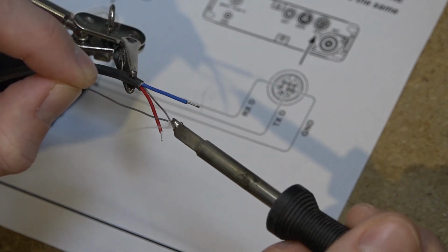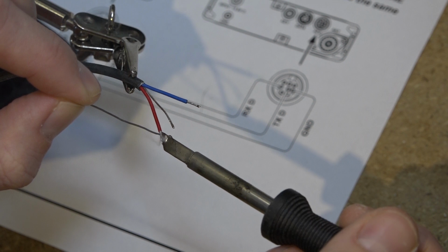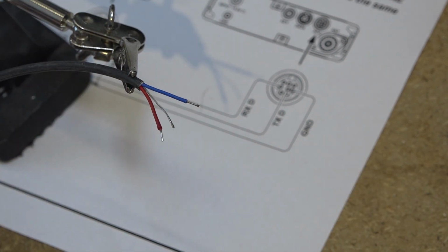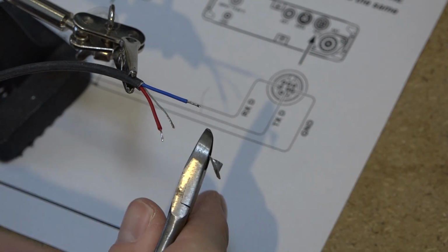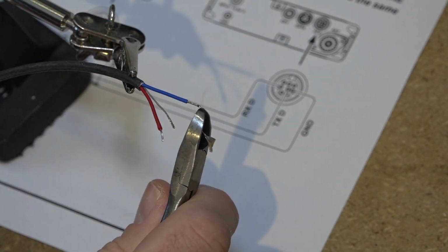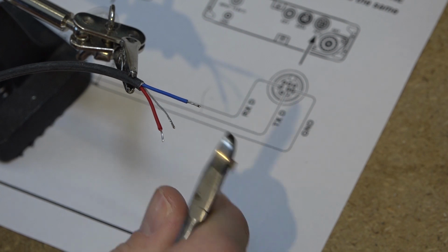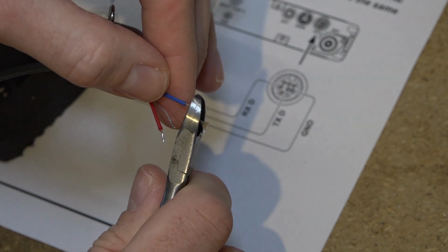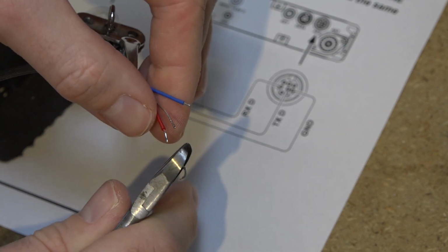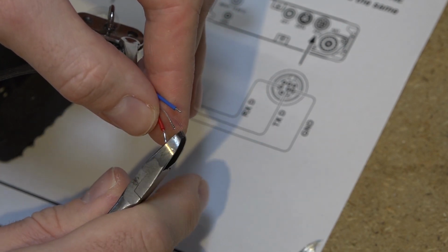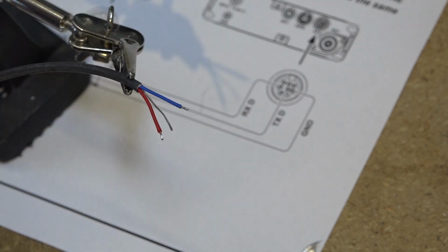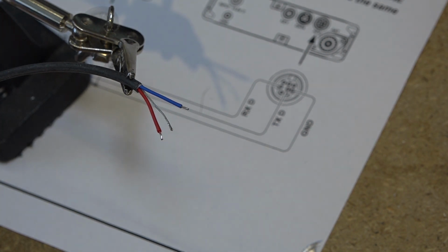and to prepare it. Now, what you'll probably want to do is on those inner conductors especially, now that you've tinned it, just shorten it down. You probably only want a couple of millimeters of exposed conductor, so you can just chop those down a little bit. You don't need an awful lot at all. And the more you have, the more likely it is that you'll short together these pins in the DIN plug because they're quite close together.